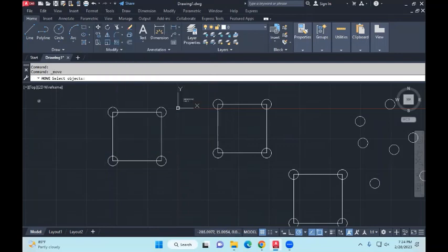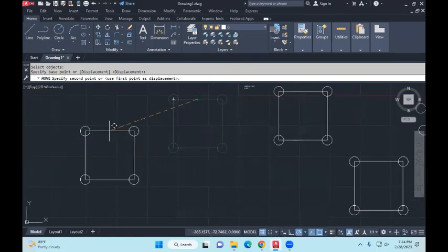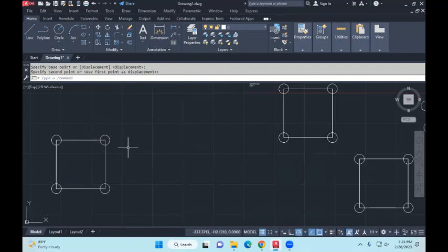So click on that. Same thing, it will ask you to select objects. I want to move this somewhere else. I have selected my objects, hit enter. Same thing, you pick a point where you want to move from. So I want to move from the midpoint of the top line. Specify the second point means you're moving from where and to where. If you're moving this chair to the back of the room, your first point will be the front of the room and the second point will be the back of the room. So specify the second point, there you go. So I moved my shape, isn't it? So try it out, try to move objects or shapes, or try to move your drawings, try to copy your drawings.